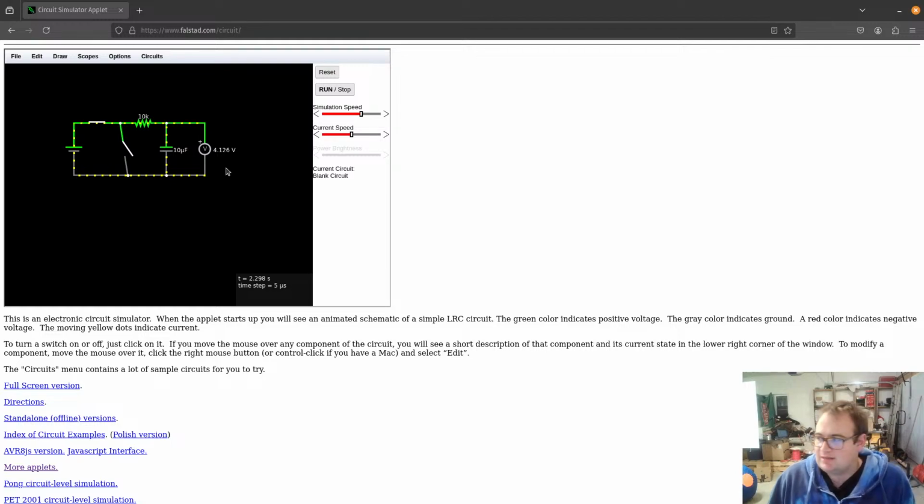But that is because if you go look at the textbook, the actual formula for the voltage, the charging, the time constant that people use, well, it's an exponential, so it isn't exactly linear. But the general rule is that in 5 what they define as time constants, which is RC, that's the time constant, is R and then C. You get what I'm saying. It's basically when you increase either the capacitance or the resistance, the length of time necessary to charge or discharge will become more.